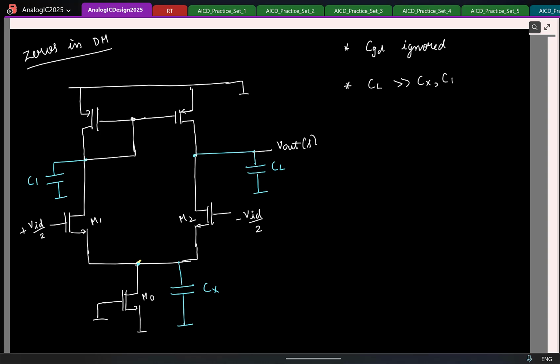Now, we already saw before that it is the R0 of these two transistors that couple the information from the asymmetrical drain node to the source node. So, if I assume that the R0 for the NMOS transistors here is infinity, then whatever asymmetry is happening here is not coupled to this node. Correct? So which means then what can I say about this node now?